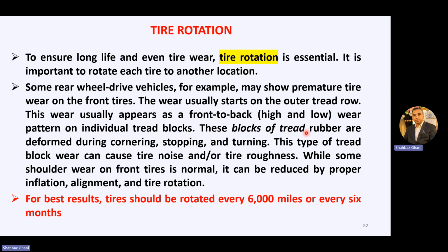These blocks of tread rubber are deformed during cornering, stopping and turning. This type of tread block wear can cause tire noise and/or tire roughness. While some shoulder wear on the front tire is normal, it can be reduced by proper inflation, alignment and tire rotation.